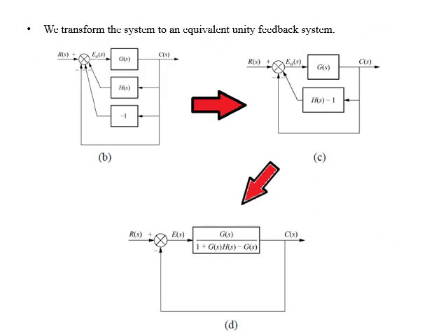So what to do here? We are going to remove the feedback. We are going to convert the system to unity feedback. How to do this? To convert the system to a unity feedback, we will get the system as you see. This is the system. I will depend on colors here to make it clear. This is the original system. And we will add a feedback of -1 and another feedback of +1. That means something like an equation: we add 1, we subtract 1. That's how you can look at it.